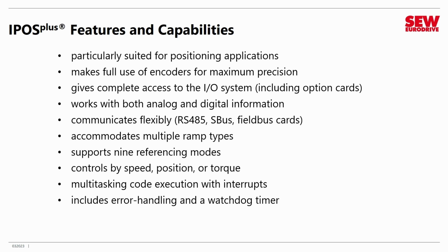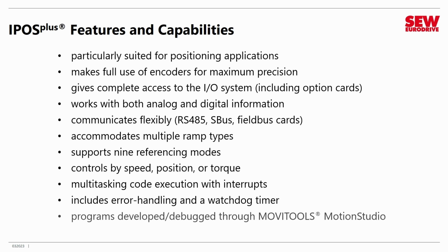Maybe you want it to stop in some controlled way and handle the error in a very specific manner. That's possible. Watchdogging allows the VFD to automatically restart itself if it should crash for some reason. That's another handy feature because sometimes you don't want to have to send someone to a dead VFD to manually restart it. So again, that is possible.